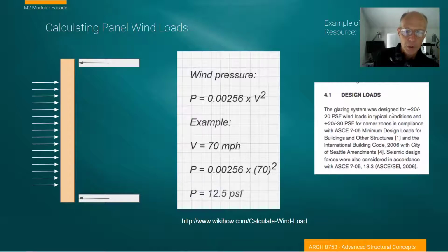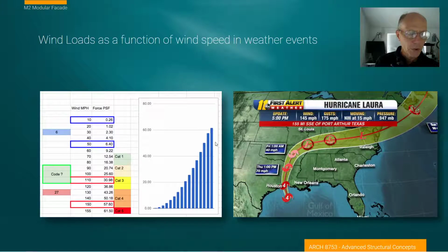And also what's unique about this is that it's plus 20 to minus 20, which indicates that not only do we think about the forces from the wind load, but the negative pressure that's created in high-speed wind systems like this. So there can be just as much pressure pushing out on one side of the building as there is on another face that's experiencing the wind. But these numbers correlate very closely with these, so I'm comfortable with using this calculation.